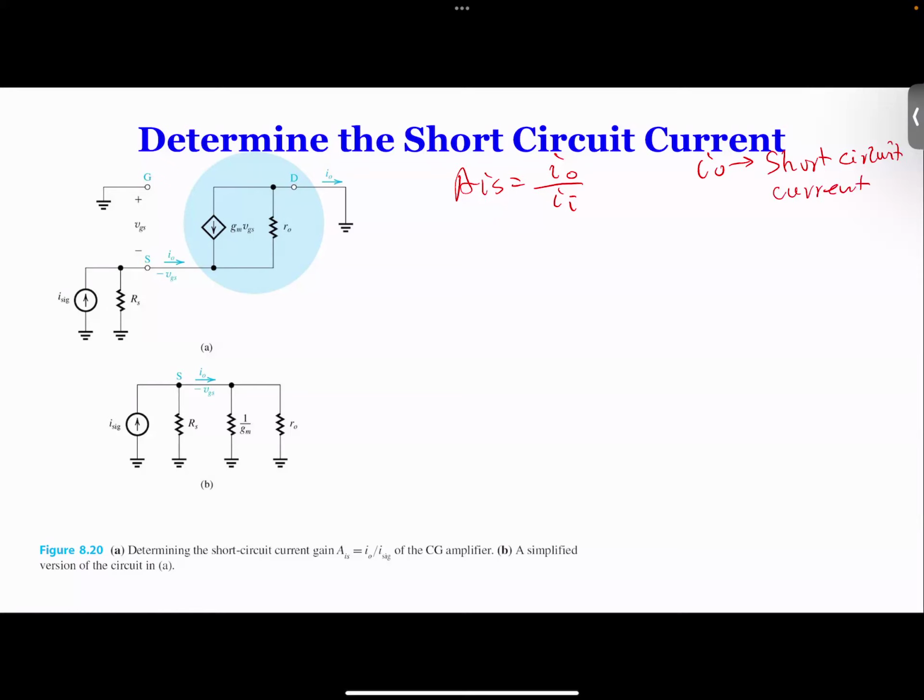So we still have the input. That's the equivalent circuit we had. And then we short the output. So now we have input current coming in and that. Now you look at this circuit, it's a very interesting circuit because the top is grounded and here's the ground too. So basically, you take the top circuit, you simply flip it. Move the ground to the bottom, what happens? You get all this connected to ground. This connected to ground, this connected to ground.